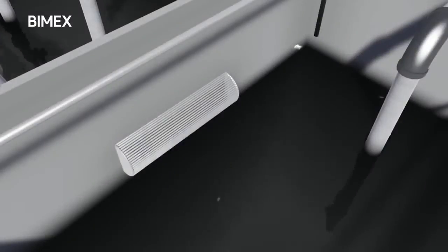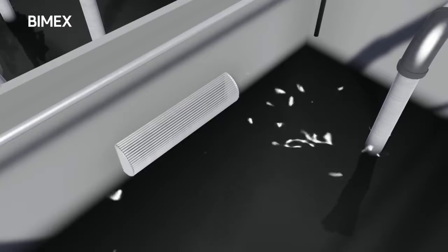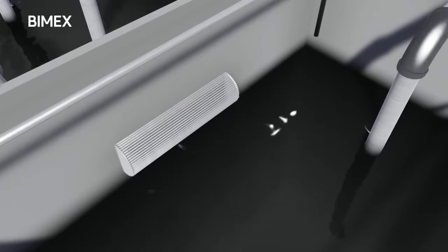The aeration system causes the biomedia to be mixed into the water and supplies the required amount of oxygen the bacteria need to grow and thrive and consume the organic waste coming with the wastewater stream. To ensure that the biomedia stays inside the aeration tank, a perforated screen is used to retain the biomedia and transport the wastewater to the secondary clarifier.